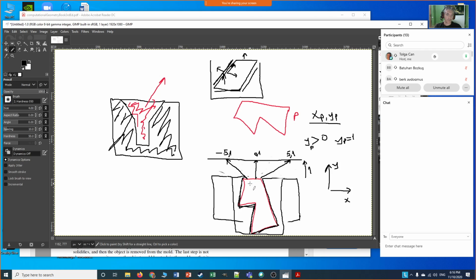So given a particular top face, if the top face of the mold is fixed, our goal will be to figure out, considering all the remaining faces of the polygon, whether it is possible to pull the plastic outside the mold by choosing some pulling direction. By the way, for this one, I think the solution may be infeasible.